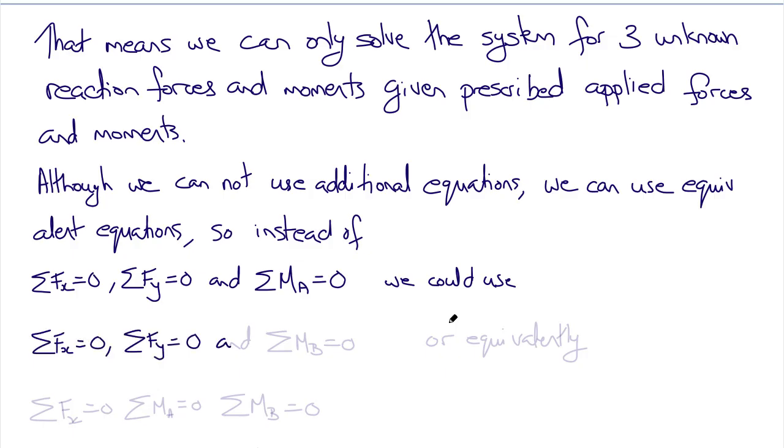Or, equivalently in this problem, we could actually use that the sum of the x components of the forces equals 0, the sum of the moments about point A equals 0, and the sum of the moments about point B equals 0.